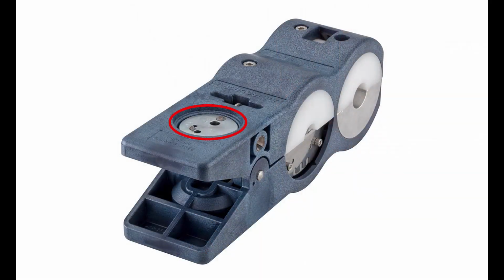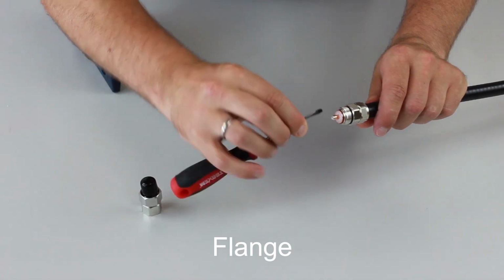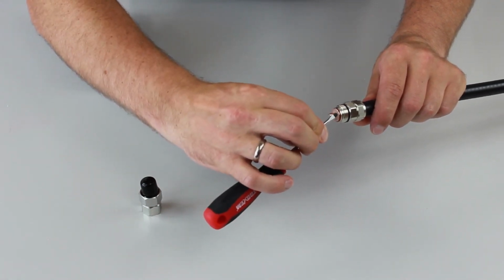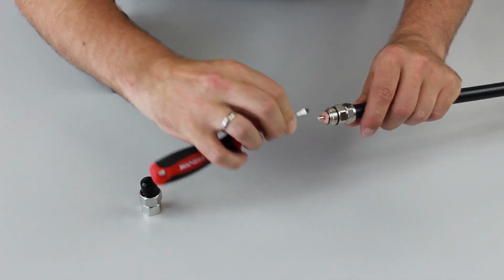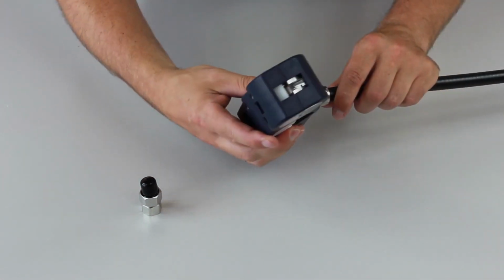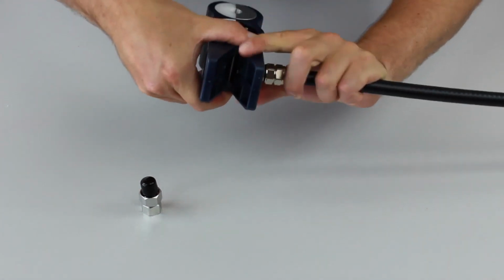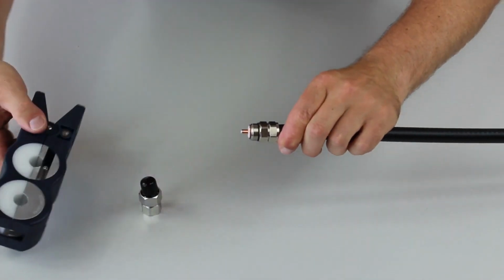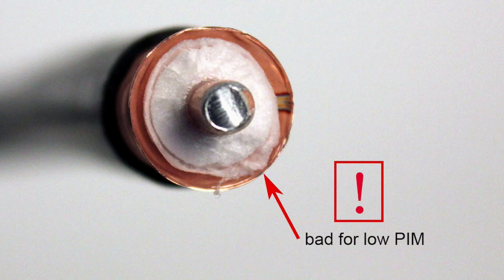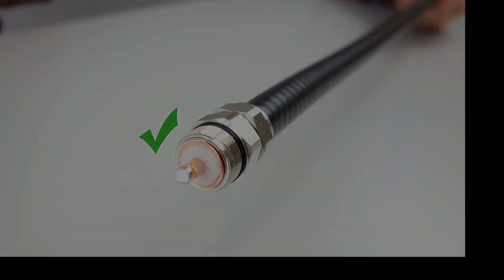Use the marked device on the Uniprep tool to flange the outer cable conductor. In order to obtain a good base for the flanging tool, create a free space between the dielectric and copper outer conductor beforehand. Widen the entire copper outer conductor. It is essential that there are no dielectric residues on the widened copper outer conductor for a low PIM connector assembly. Remove any residues if necessary and take care not to scratch the conductor.